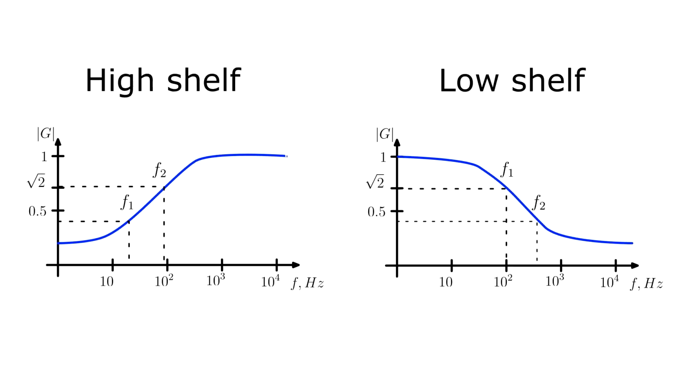The last type of filter is the shelf filter. It's similar to the high-pass and low-pass filters, but it attenuates the signal to a determined value. Shelving can be used for the redistribution of frequency balance and can be applied as a booster or attenuator for a certain frequency range. It's characterized by a lower frequency, upper frequency, and gain factor for shelves. I use a 5 dB shelf filter for my voice in records to boost the bass. Without this filter, my voice sounded less expressive and colder. This is a common trick for speech recording.